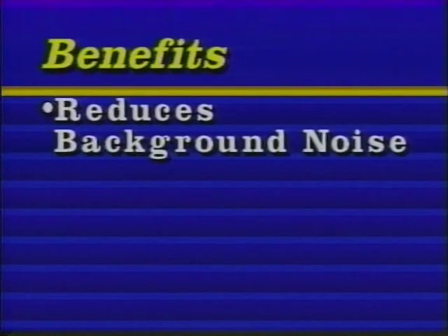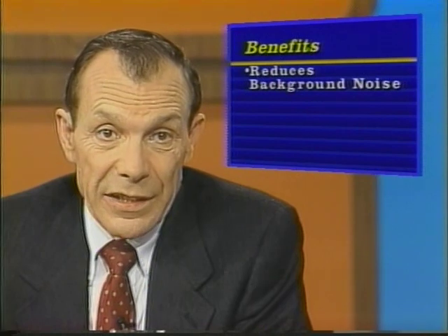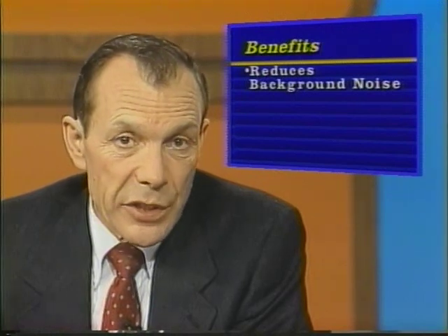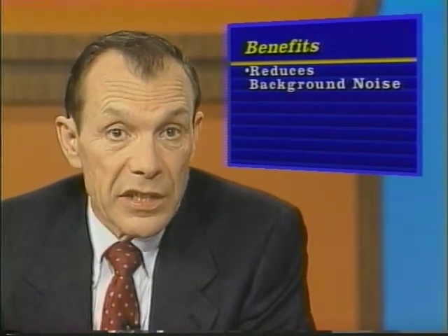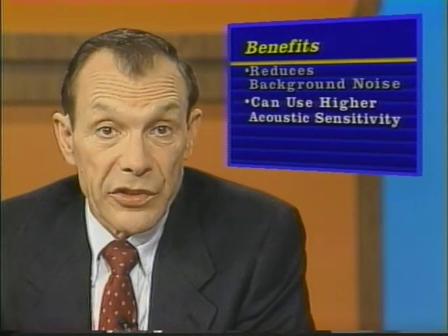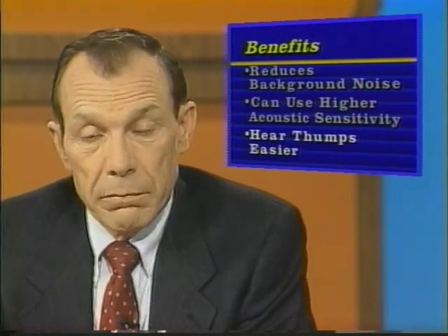One of the first benefits you notice with an earth contact microphone is the reduced amount of audible background noise. This makes work in a noisy environment much easier. Since a soft material doesn't vibrate like a hard surface, sound waves hitting it don't travel sideways through it, and noise produced a short distance away is lost before it can reach the steel rod. I use the earth probe microphone in the dirt at the edge of a sidewalk, even if the cable is under the sidewalk. I can increase my acoustical sensitivity since I do not have the background noise to fight, and I can hear thumps much easier.